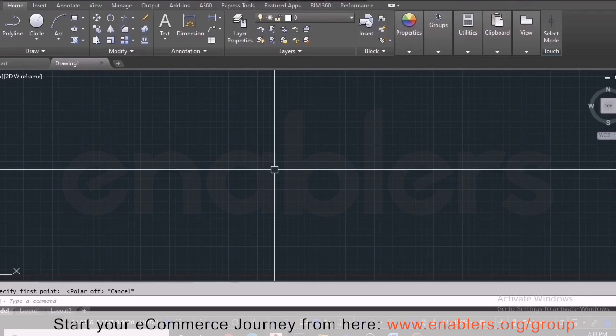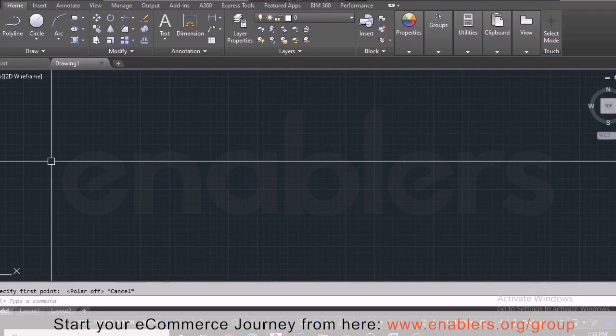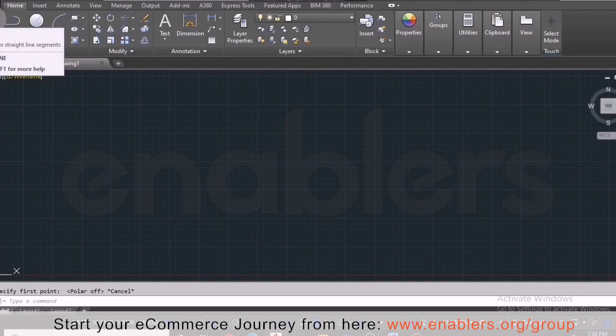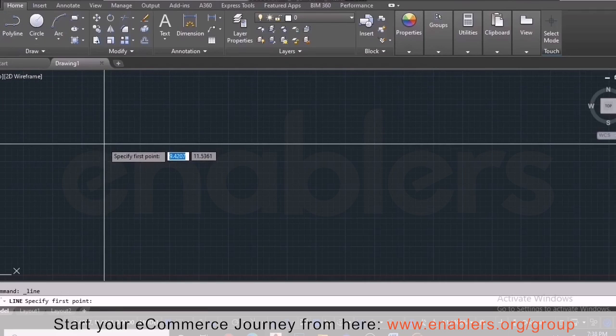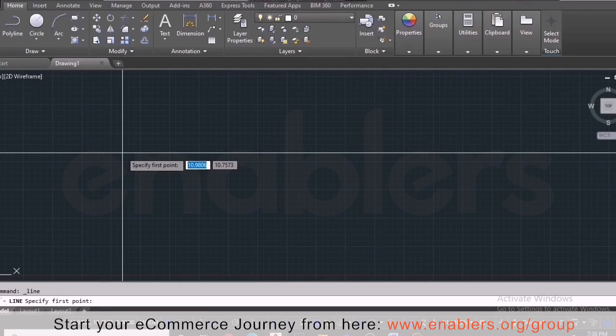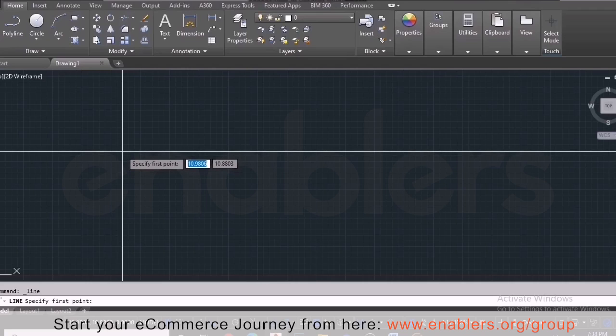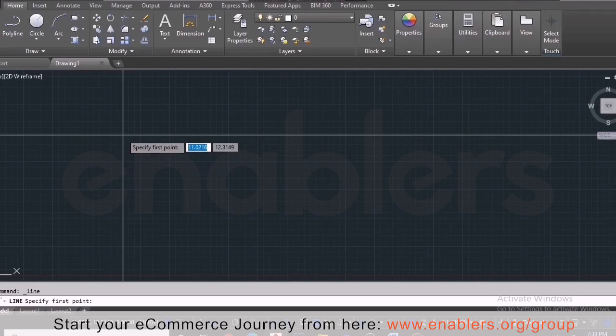Okay, let's start our very first drawing quickly. For that we have to go to the line tool and click on it. Now you see that after activating the command, we have two intersecting lines; this type of cursor is called a point cursor. Right next to the cursor, you will see this kind of bar called the dynamic input toolbar. If you don't have it, that's fine. You can bring it up using the F12 function key, and you can also make it disappear with the same key. Right now I am not using this bar, so I will make it disappear.